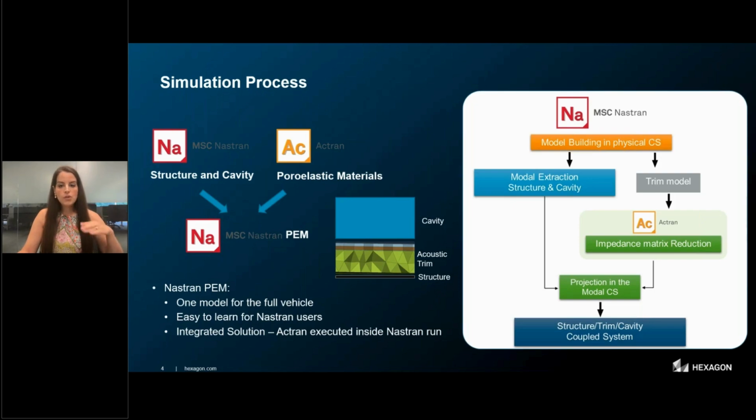To streamline this process, we usually begin by identifying candidates for the reduced grids, key points where the interactions are most significant. And after we identify those points, the impedance matrix is reduced in the physical coordinates, which simplifies the system, okay? And we still capture the essential dynamics of the system as well. And then what we do is we take the reduced impedance matrices, or RIMs as an abbreviation, something I'm going to use in this presentation moving forward, and we project them onto the fluid and the structural model basis.